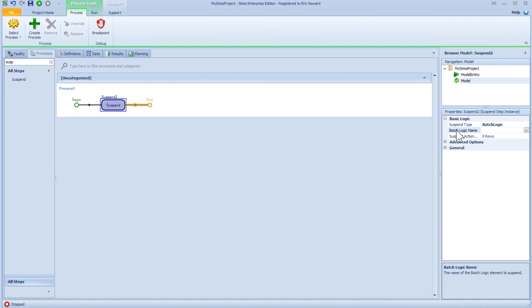This means that the parent and member entities will reside in the input queues of the combiner and not attempt batching. If this new property is set to false, parent and member entities will continue the batching process and will be removed from the parent and member input queues, but will not move through the combiner object until the failure is repaired or work schedule changes. Note: the default value of this property is true for new models, but false if updating an old model, as that was the implicit setting in the previous object versions.